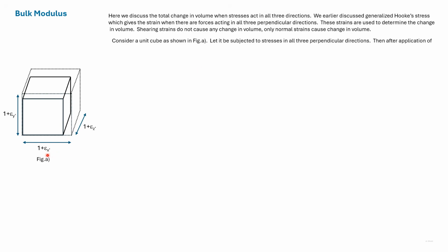Here epsilon x dash not only includes the strain due to sigma x, but it also includes the lateral strain due to sigma y and sigma z. Similarly with epsilon y dash and epsilon z dash.